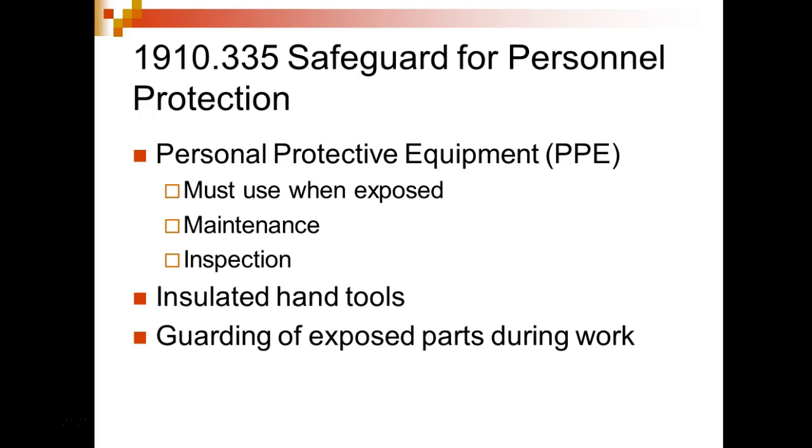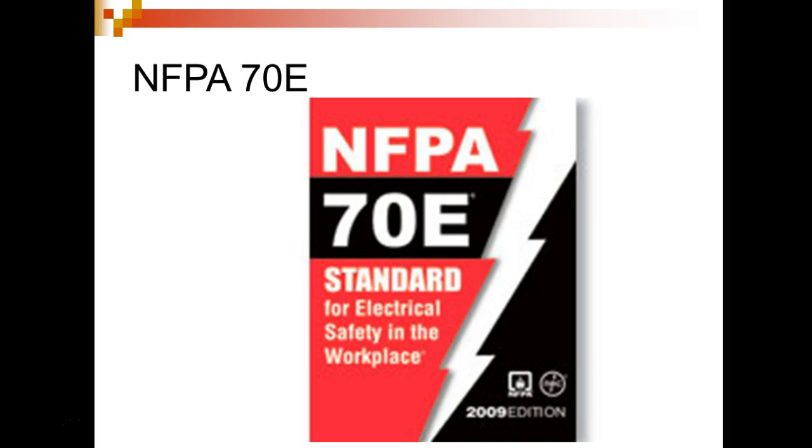We're way down, still low on the scale, but even in our place, since we're going to be exposed to 120 volt outlets and stuff like that, we're going to require certain PPE. Now it's very low, but stuff like shorts and sandals is not going to be allowed in the slab. Understand? Safety devices. So it's not very much. When you take motor controls now, you're going to have to buy some leather gloves to work over there. To make measurements inside that 208 cabinet, you're going to have those. Anytime you make voltage measurements, you'll have to put on your gloves. Anytime you're rewiring or stuff, because we're a class Z.